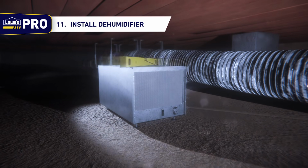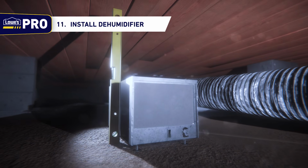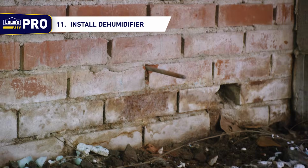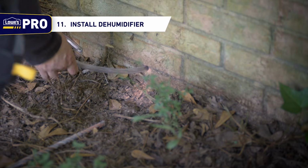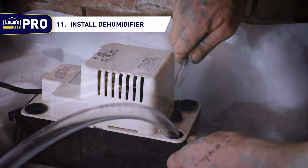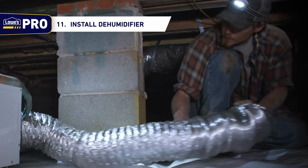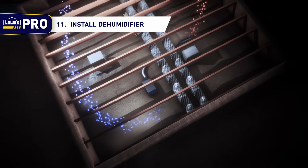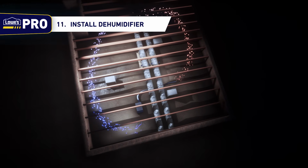Step 11. Install dehumidifier. Make sure to use a level when installing the dehumidifier so that accumulated moisture flows correctly to the pump. Drill a small hole in the foundation below the band seal for the pump drainage hose to reach the outside to drain properly. Securely attach the condensate pump to the dehumidifier and attach the drainage hose to the condensate pump. Run an uninsulated duct from the exhaust on the dehumidifier to the tightest area of the crawl space in order to create a convective loop of dry air and moist air inside the crawl space.